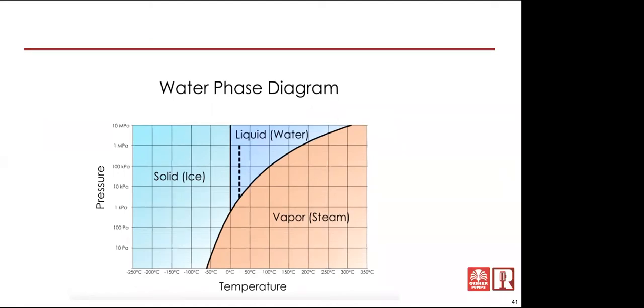So inside this pump, when we create a lot of turbulence because it's not operating the way we would like it to operate, maybe we've starved it, maybe we've closed off the discharge valve enough that we're causing a lot of recirculation and turbulence inside that pump, we can get to areas where that pressure dropped below that level, even 1/10 of atmospheric pressure.